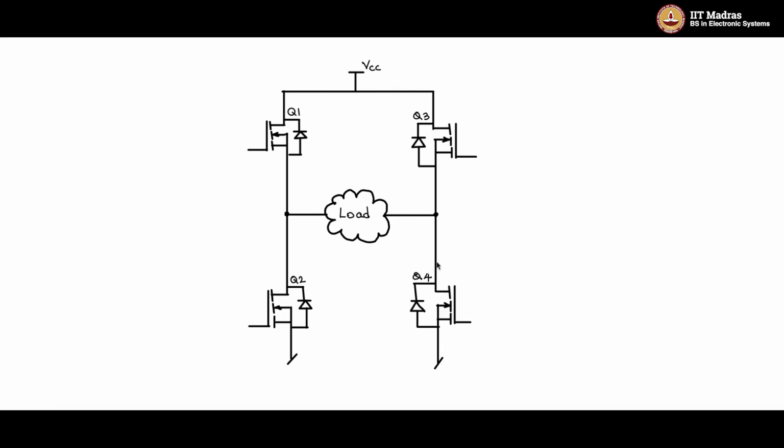and by switching the different MOSFETs, we can get pulse width modulation here. Almost the majority of the loads will be switched using full bridge circuit topology, and by the pulse width modulation strategy that we discussed previously.